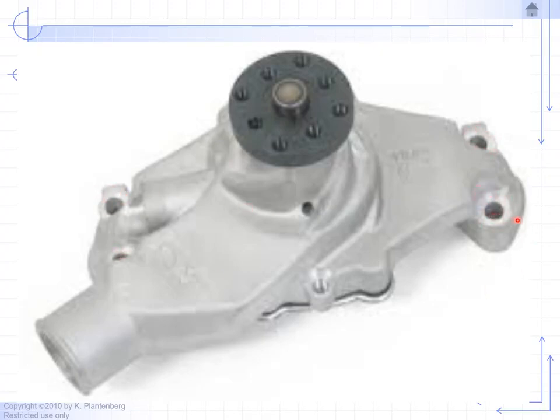Before they were machined, you had a contoured surface here. So you come in and drill your first hole, then you come in with your second, counterbored hole, and it's going to remove some of that rough surface with contours. So you're guaranteed to have this surface parallel to the base. Same thing with the other four. You have the top surface of the counterbored hole parallel to the base.